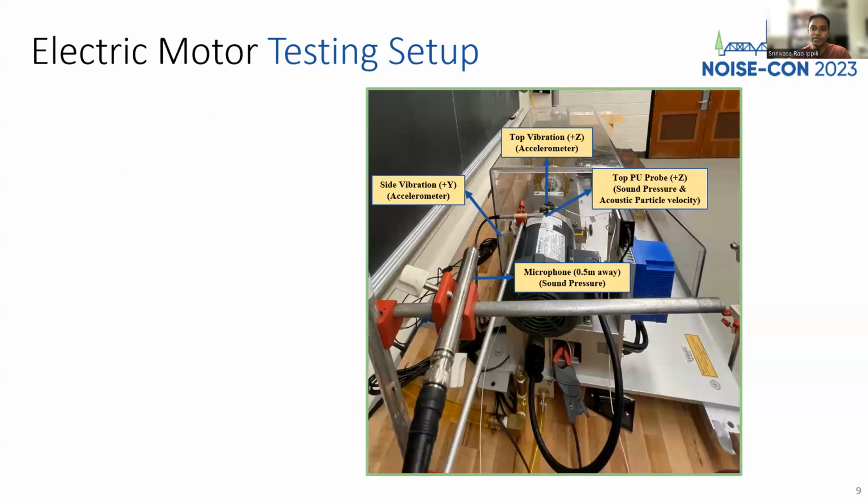Vibration historically has been the only parameter used for machine health monitoring, but using accelerometers can pose mounting, calibration, and placement issues. Non-contact acoustic transducers, such as particle velocity sensors, can provide a solution to these problems in those applications. They can measure vibration information acoustically and characterize the vibroacoustic behavior even in the presence of background noise, thereby enabling the identification of specific sources despite other acoustic sources nearby.